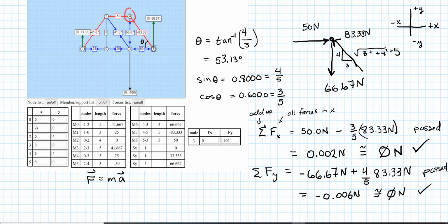Make sure with this lab that you just pick the one pin where you have those highest forces. We just want to look at that one pin where it looks like it would be the most likely failure condition. And then when you test your wooden trusses or whatever you were able to make them out of, see if that's where you failed. Did you fail at pin 4? Or maybe did you fail between pin 4 and pin 5 due to that really high compression force?